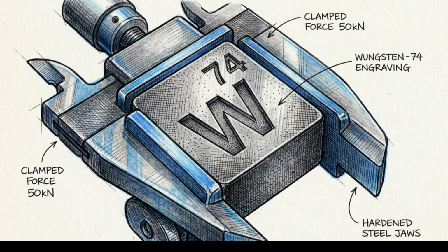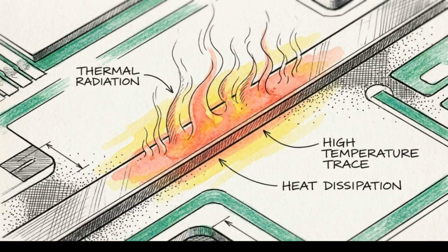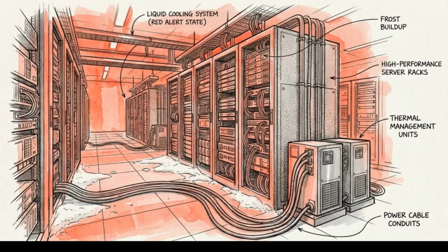Generating this spin polarization dictates a rigid physical requirement. The base material must possess strong spin-orbit coupling. Strong spin-orbit coupling is found almost exclusively in heavy metals, like tungsten or platinum. These heavy metals inherently suffer from high electrical resistivity. Pushing the necessary current through a highly resistive heavy metal generates excess heat and drains power. In large-scale integrated circuits, this thermal and power draw creates a hard physical bottleneck for energy efficiency.